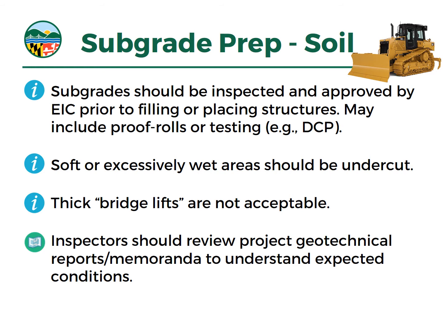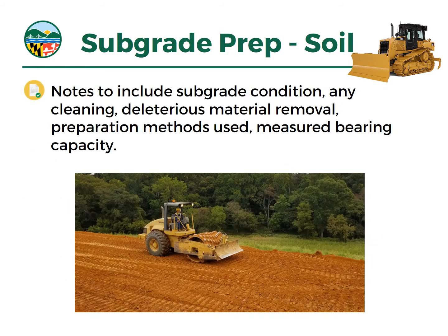And inspectors need to be aware of that, and they should review the project geotechnical reports to understand what conditions they should be seeing in the field. Because if there's a change, they should let the designers know that. But they should also be prepared. Is this a sandy subgrade, a clayey subgrade? Do we expect high groundwater? All of those things can help inform recommendations in the field for how the subgrade is prepared.